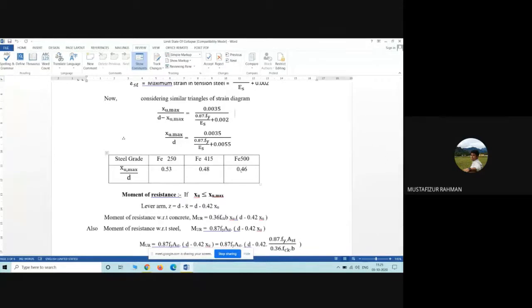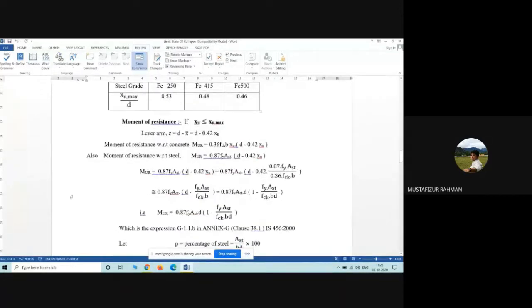We got up till now the actual neutral axis depth and the limiting neutral axis depth, right? I have told you this chapter is related to your strength of materials, bending stress distribution, which we are utilizing. So now we are to find out the moment of resistance. Bending moment is because of the external load, and moment of resistance is the resistance offered by the cross section, internally.